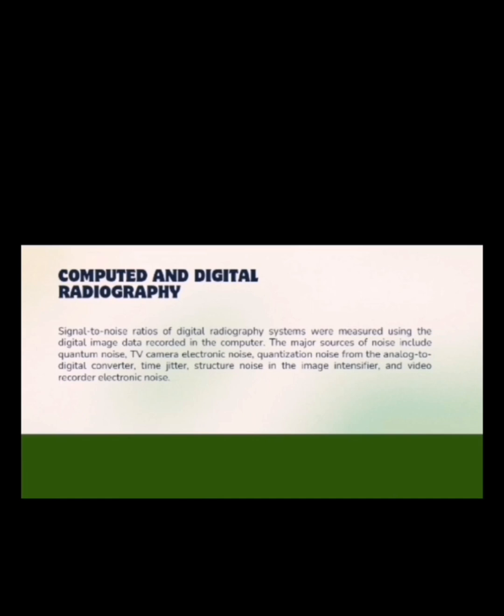The major sources of the noise include quantum noise, TV camera electronic noise, quantization noise from the analog to digital converter, time jitter, structure noise in the image intensifier, and video recorder electronic noise.